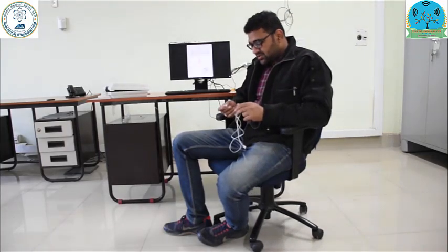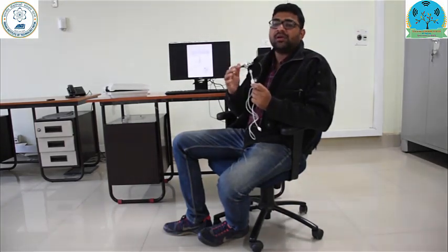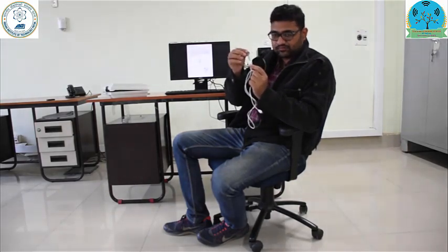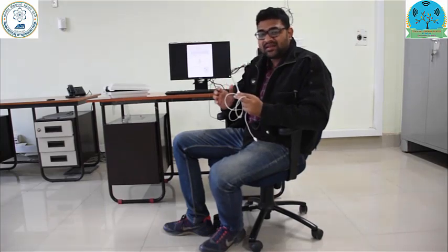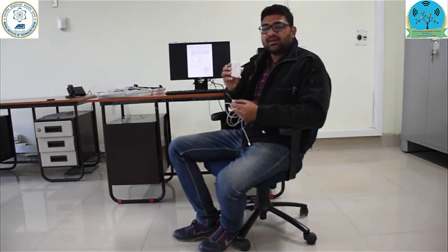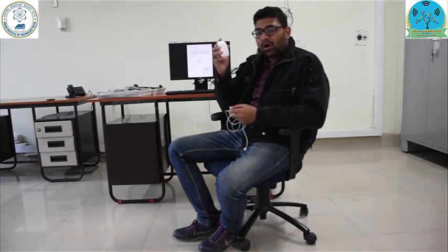So to show one of the sensors, this is a force response measurement sensor where we can identify the amount of force a particular human part or human body is exerting. We use our thumb or maybe limbs, and we put pressure on this thin film strip which measures the amount of force exerted on the sensor. This sensor can be deployed in a biomedical signal flux environment, which at its heart has a microcontroller. As I discussed, any sensor node will consist of a microcontroller, and our biosignal flux kit also has this microcontroller. This microcontroller has 8 channels in which we can deploy the 8 sensors. Also, at one time we can measure 4 to 5 sensing data from any human body activity.